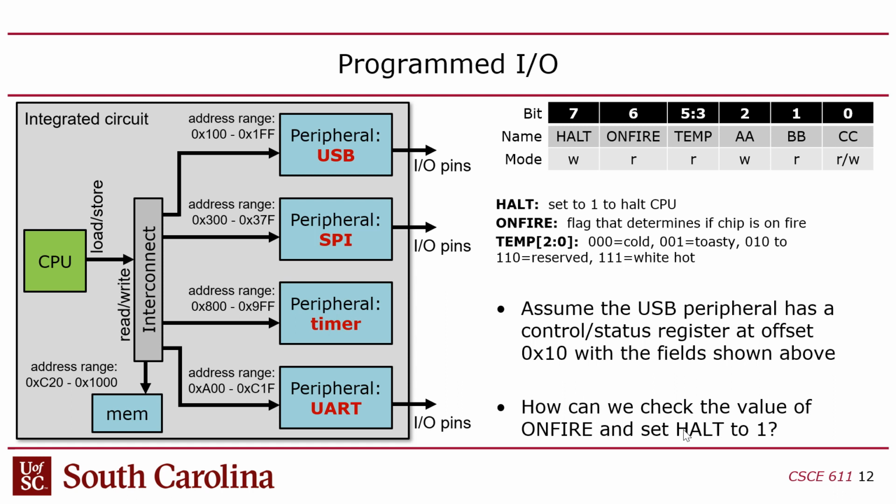The problem is that every instruction set architecture I've ever seen doesn't work that way. You can only write words. You can load an immediate, which is a word, and it loads a whole register. Everything is registers, so if it's a 64-bit processor, you're dealing with 64-bit values. There's no way to put a bit into a value, at least not in one instruction. You have to use multiple instructions and tricks to do bit manipulation.